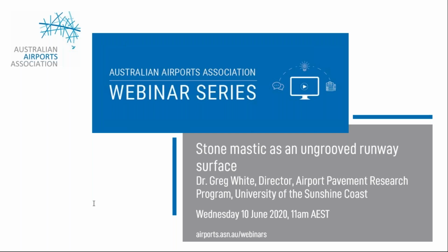And another one: how does SMA perform under rainfall events with relatively flat grades on runways when compared to a grooved runway? Well, in both cases, the grooves, or in the case of SMA, the surface texture, isn't predominantly there for drainage in terms of the whole pavement draining. It's really there to allow an escape path for the water that is trapped between the tyre and the pavement surface.